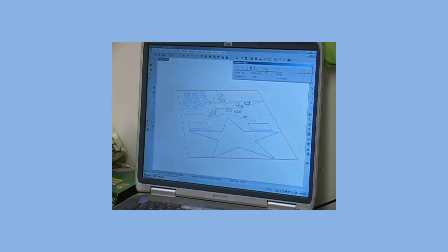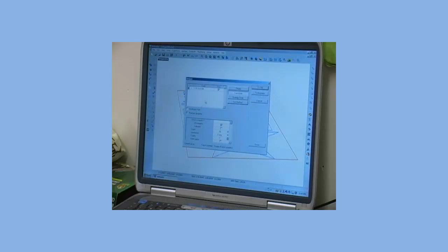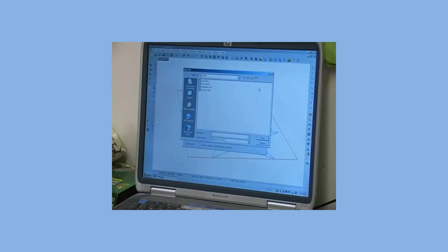Okay, this pretty much is good enough for me. I'm happy with what we have. I'm going to pause it, click Done, and I'm going to create my file by going Machining, Output, to File, don't change anything here, and I'm going to call this Coastline, or let's just call it Coast. And save it. It should say .ncc.